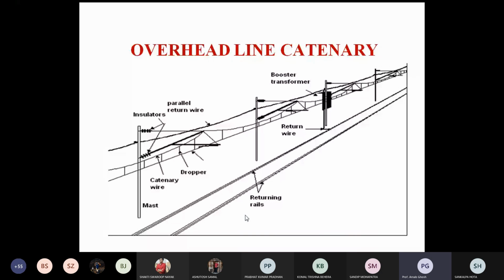So there should not be any potential drop in that earthing. Still there is a potential drop. As per the level of earthing, the potential also will change. Normally it is 0.4 volt and the resistance is very low. We use a meter for measuring that earth resistance. That meter was discussed in the instrumentation class. The standard process was there, so you can go for that when you are doing your measurement lab. I think that experiment has been done. So that return path you can get.